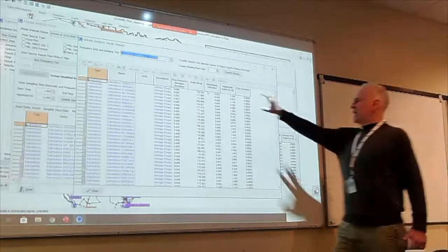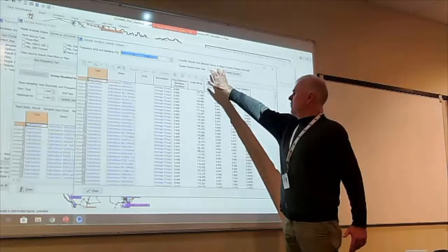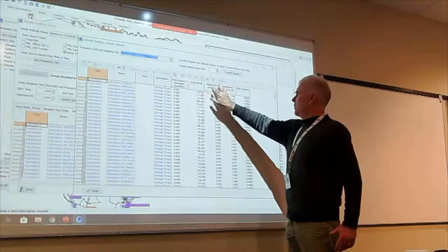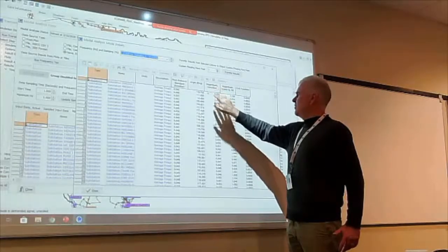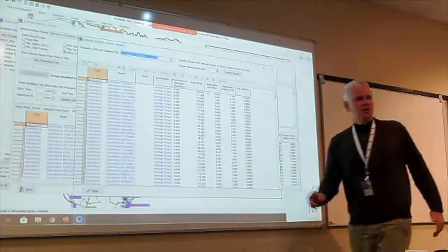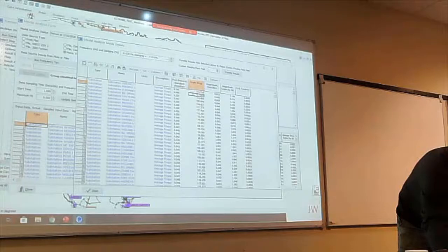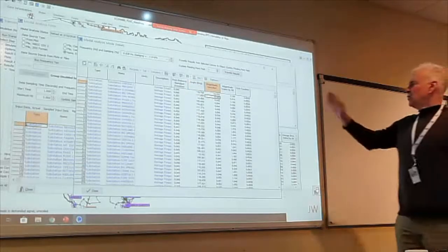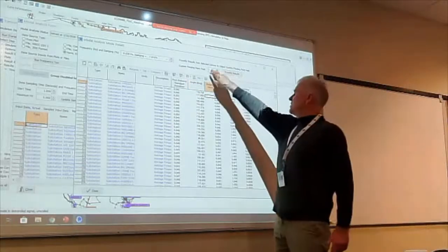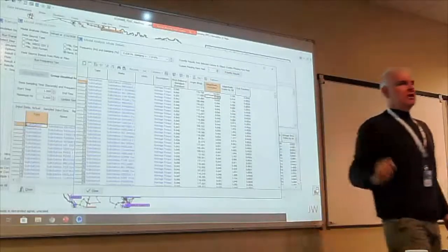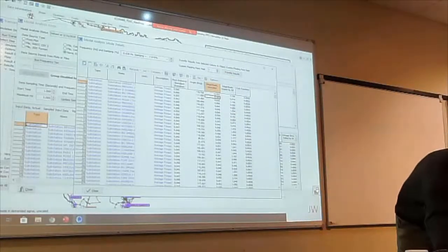We're going to put the angle in the custom float 1, and we're going to put the magnitude unscaled in the custom float 2. To do that, just click on the angle field, angle degree field, and then click on transfer results. Then click on the magnitude unscaled, change this value to 2, and click on transfer results.